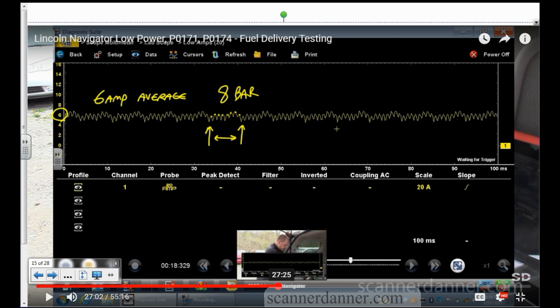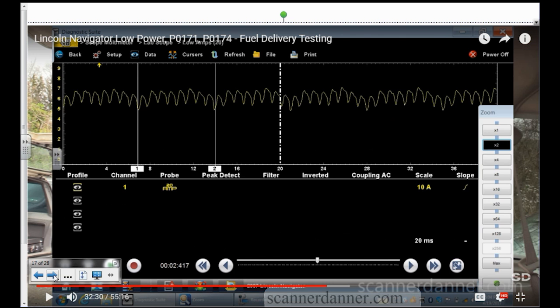What do I mean by bar? When I'm talking about the bar of the pump, I'm talking about this guy right here. That's the inside of a fuel pump motor. Those are called commutator bars. And what you'd have is a positive brush that would ride here. This would go to power, and then you'd have a negative brush that would sit here.